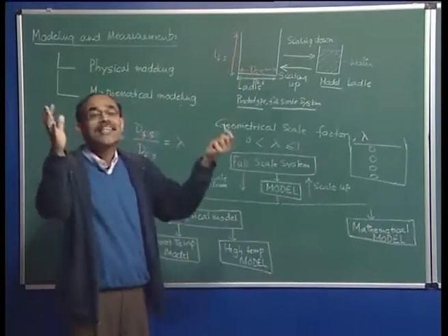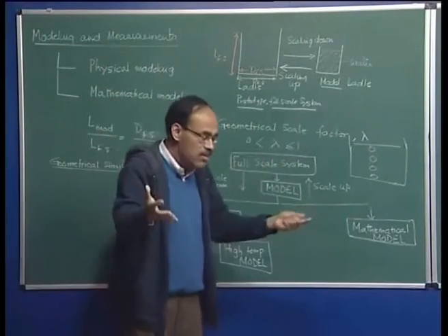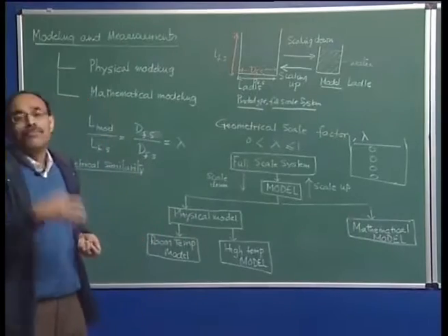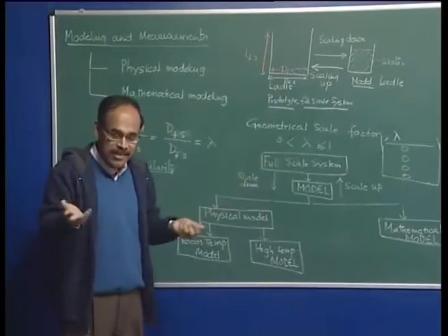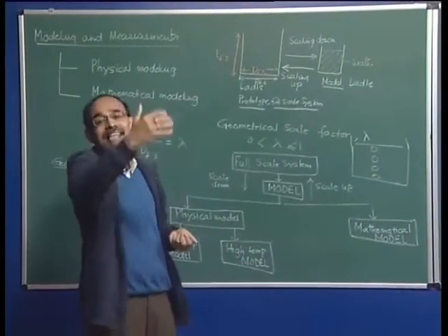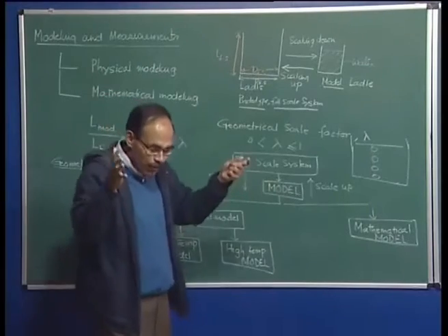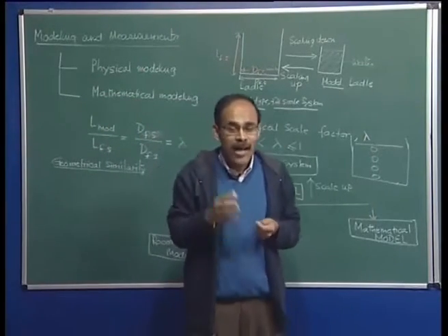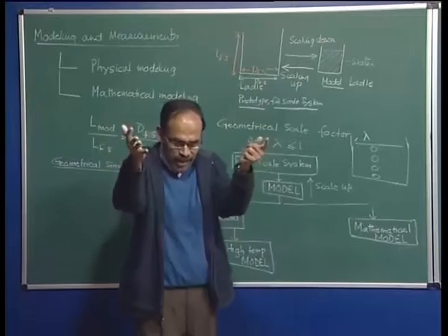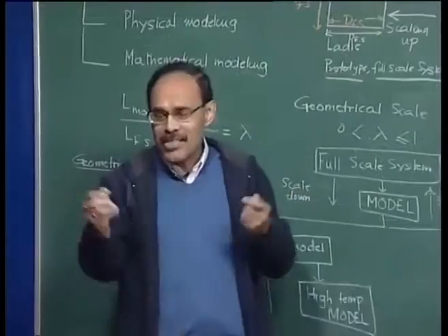Now, you imagine a tundish, for example. The tundish has refractories, and I wish to consider that tundish. I want to do a water modeling. So, I may fabricate a tundish with any material, and typically what we do is fabricate the tundish with plexiglass, which is basically a plastic, a see-through plastic, so that we can see how the water flows within the tundish when you use water. Now, in the actual tundish we have refractory linings and tundish nozzles. These nozzles undergo various different extents of hydrodynamic wear during the process. Also, we have refractory linings which wear out as a function of the number of heats.